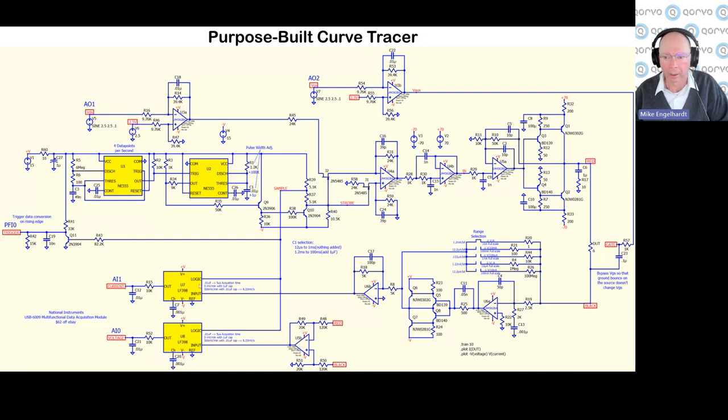I have to pulse the drain, and then I have these sample and holds. I have to store it so that the successive approximation ADCs will look at the stored sample, captured at the very end of the pulse. And then this is like an electrometer. For an electrometer, you take a giga-ohm resistor and you put it between the output and the inverting input. It's a transimpedance amplifier with a giga-ohm resistor. That's your electrometer.